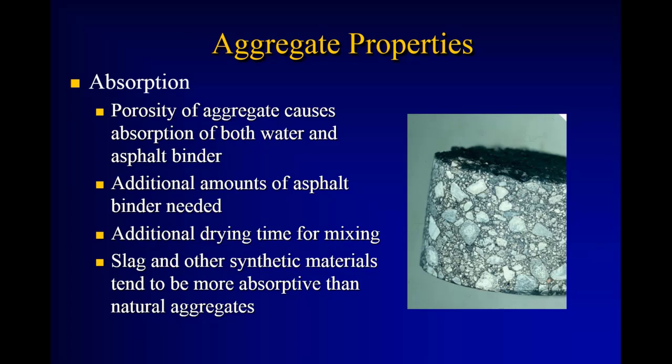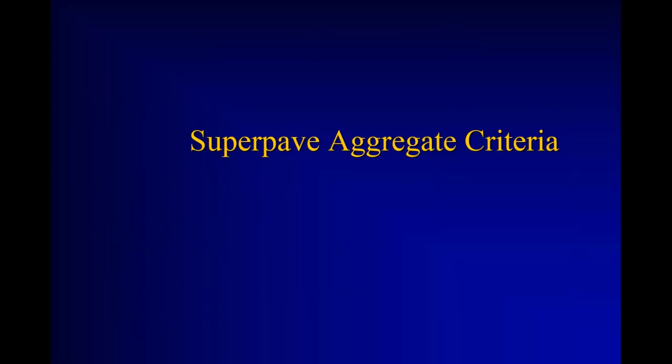On the asphalt side of it, that's our expensive product. And by the time that material hits the paver, that asphalt absorption has to occur. If not, it's going to keep occurring on any hot day afterward. And basically will continue forever, but it's asymptotic. It levels off the rate at which it does so. So it can cause issues with construction, cost issues, production issues.